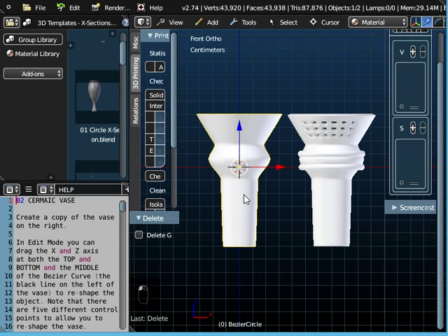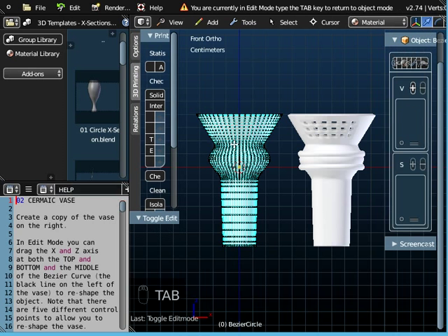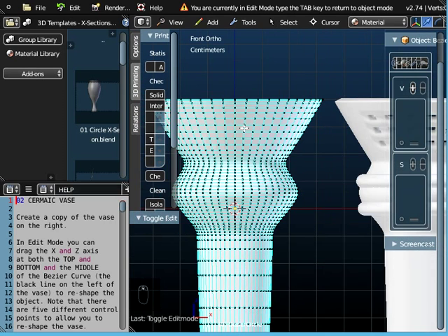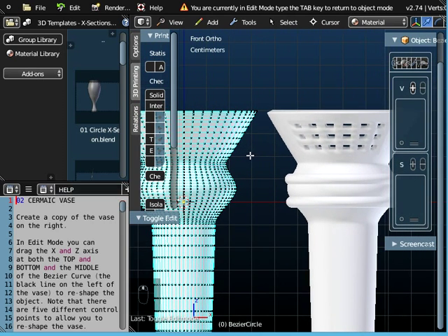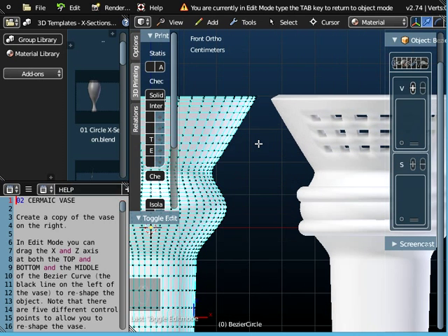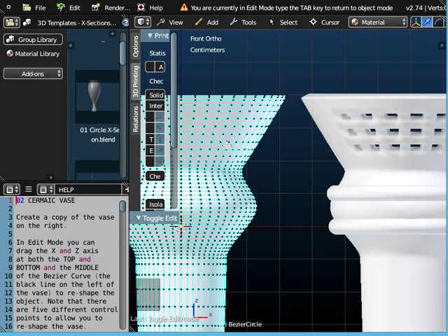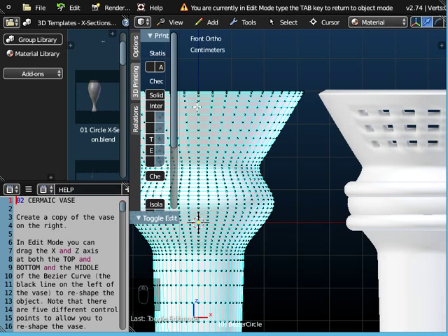Now that this is actually a mesh, if we press the tab key and go into edit mode, you'll see we can see the mesh that makes up this object. What we want to do next is recreate these holes, this hole pattern or something similar to it in the object that we're working on. So that looks like it's kind of the center line of the object. What I really want to do is highlight a face here, that's a whole rectangle, and delete it.